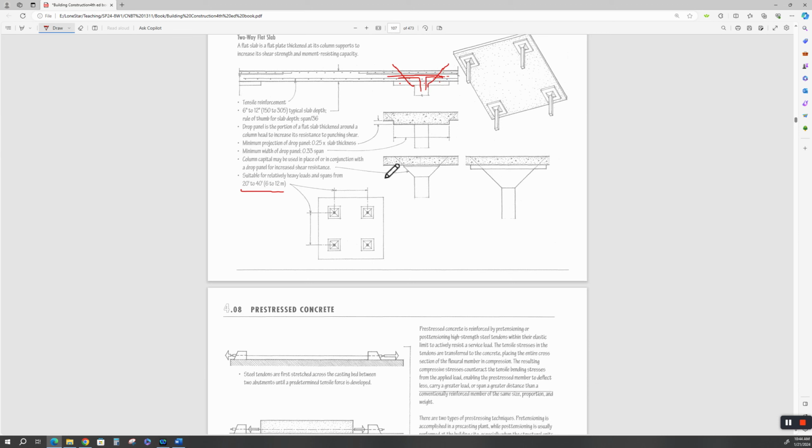Here's an architectural term. Column capital. You can Google Greek columns and you can look at the capitals they put on the Parthenon, the top of the columns, but this is called a capital. It's a bell-bottom footing upside down, right? So, of course, it's going to be a nicer looking bell-bottom footing because you're going to form this, okay? Make the architects happy. And now these capitals can be square or they can be round.